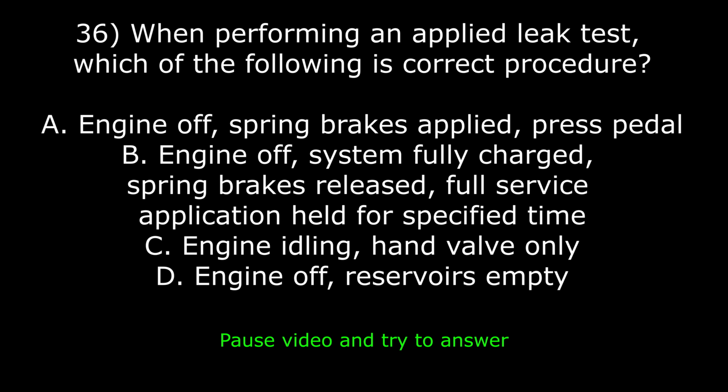36. When performing an applied leak test, which of the following is correct procedure? A. Engine off, spring brakes applied, press pedal. B. Engine off, system fully charged, spring brakes released, full service application held for specified time.